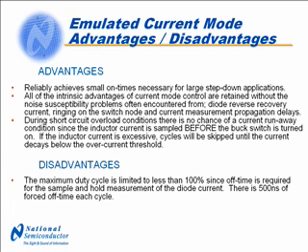If the inductive current is excessive, cycles will be skipped until the current decays below the overcurrent threshold. The disadvantage is that the maximum duty cycle now has to be limited to less than 100%, since there's a requirement for forced off time each cycle for the sample and hold. In the case of our new devices, there's 500 nanoseconds of forced off time each cycle.